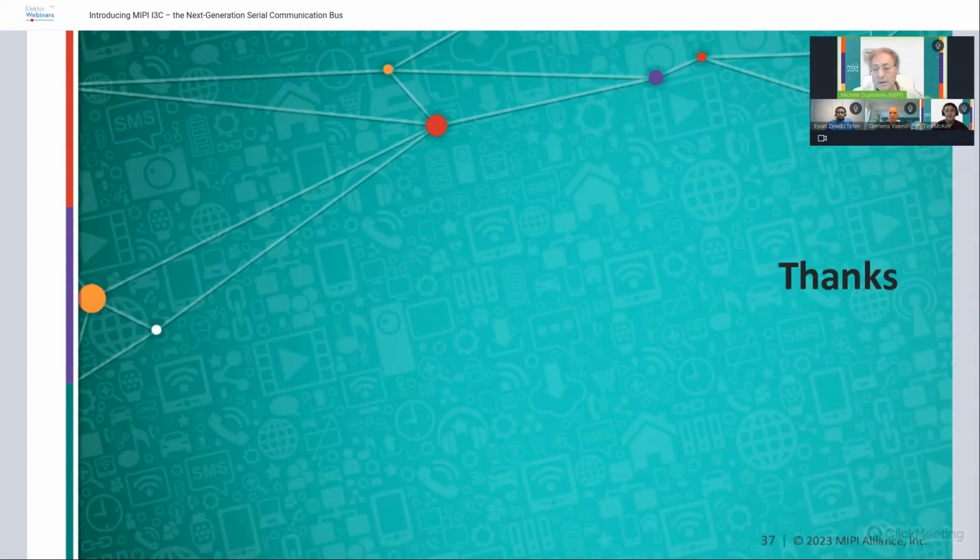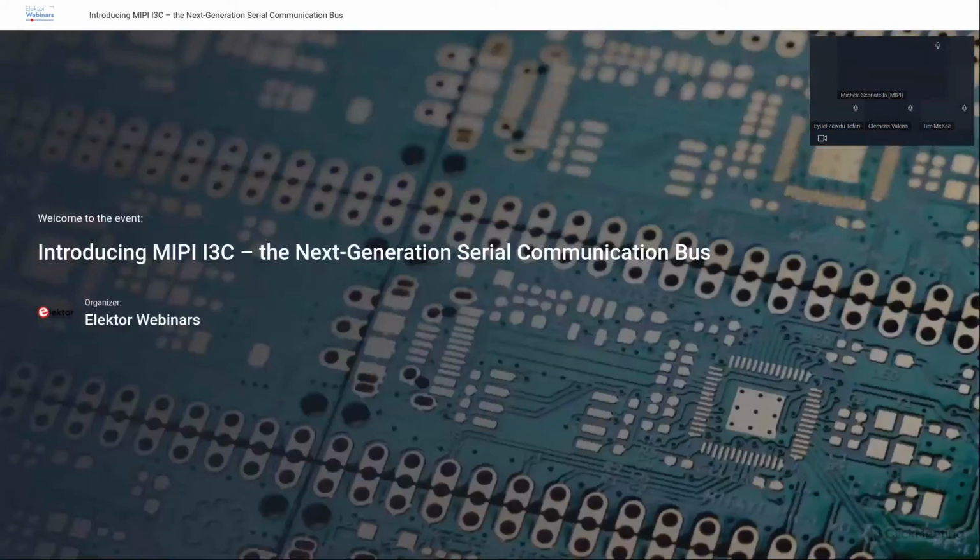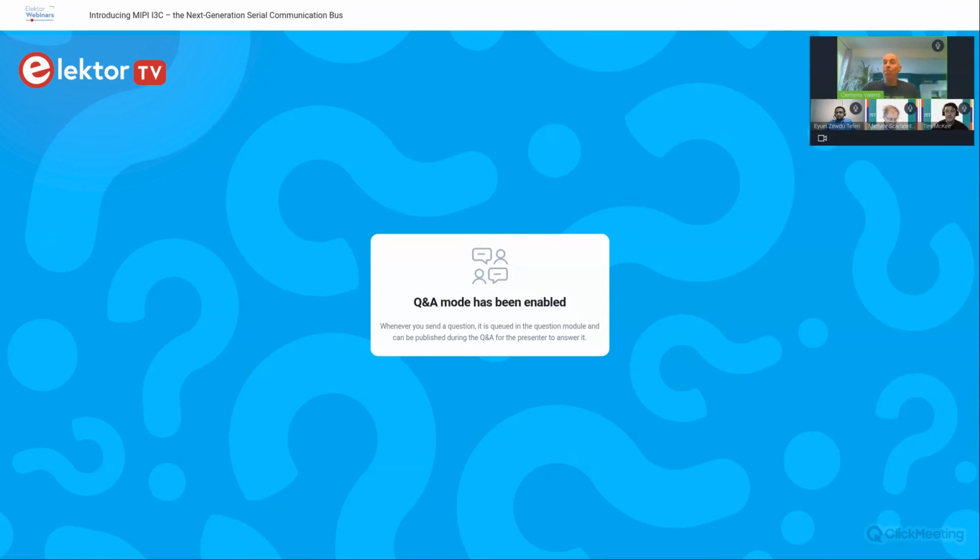So we felt that, instead of adding an extra byte for the address, 7 bits is probably enough for a configuration to be alive in a certain moment, because if you assign an address to a device, that's not blocked for the rest of its life. The addresses are reused.